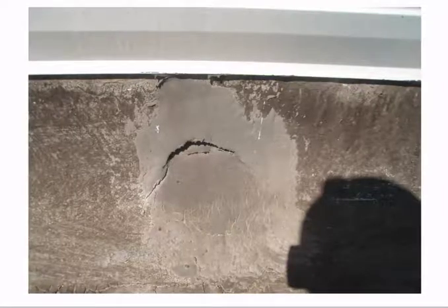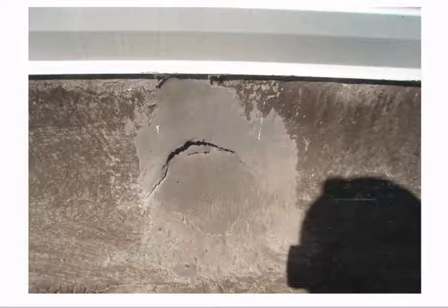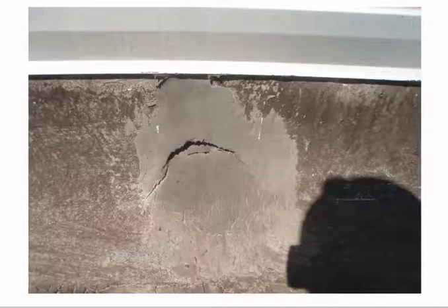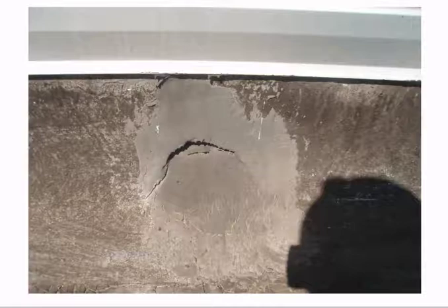It's a common issue, and the most common repair that I've seen is just people putting a layer of mastic on it, just roof cement, just packing that hole. Well, that's not a permanent repair. That's a temporary fix to get them dry and hope to come back tomorrow and make a permanent repair. The permanent repair is to prime that, clean it really good, put some asphalt cutback primer on that, and a 3-course at minimum over that. And the best repair obviously is a 5-course, get those layers built up and durable.